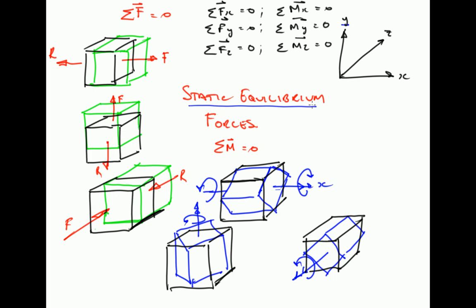Most civil engineering structures are static structures. They're not moving in any given direction or rotating about any given axis. Therefore, in order to calculate the forces, stresses and moments within those structures, we can rely on the fact that the equations of static equilibrium need to be satisfied, and we can use that to generate up to 6 equations.